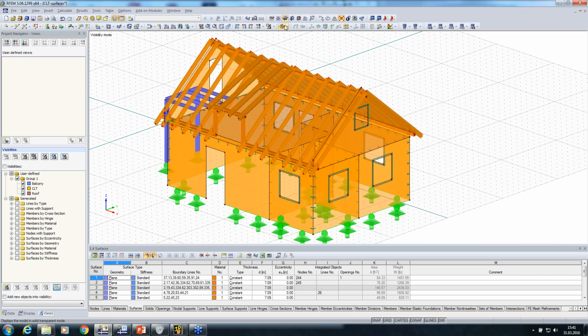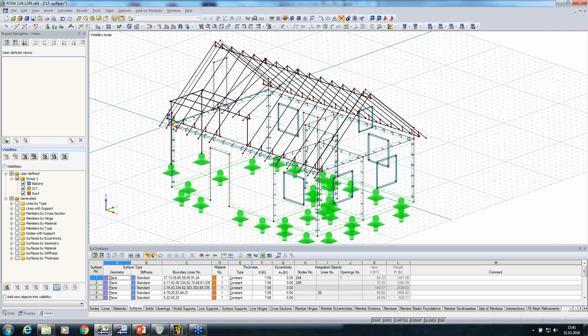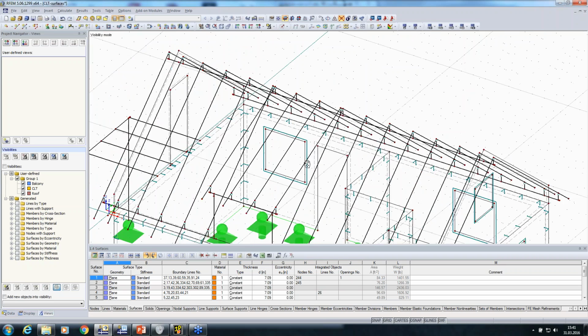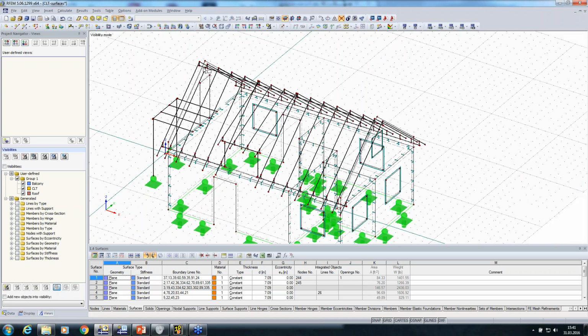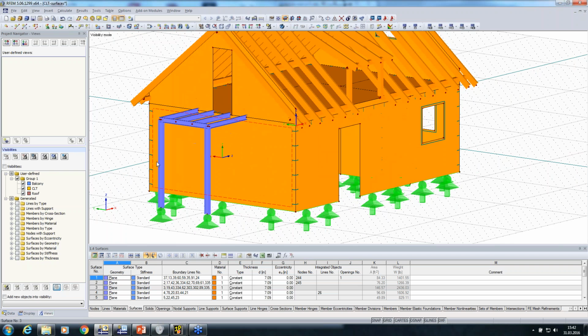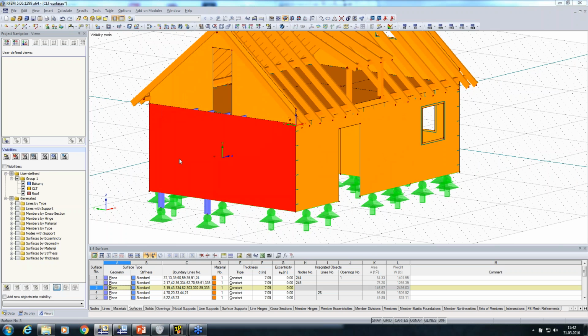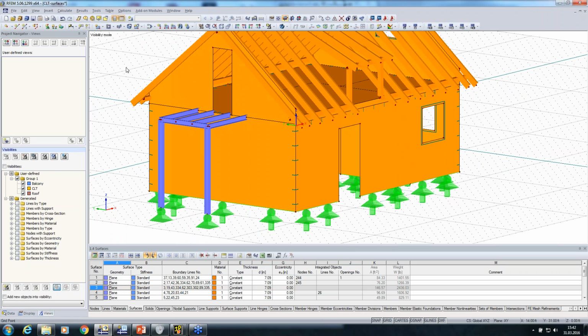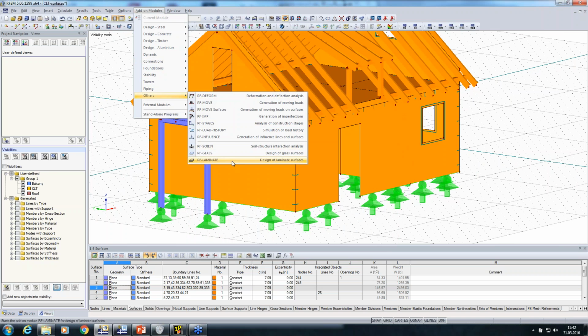So let's have a look if it all worked. That's a good hint, if it's integrated into the ridge right here. That works, looks all good. The panels themselves are now still some ordinary wood, but I want CLT panels from it. That I'm going to do via the module laminate,